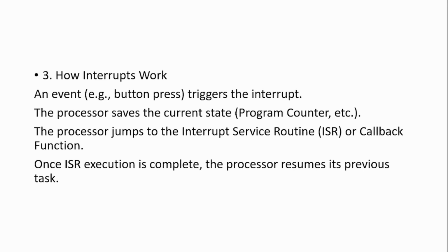I will not go into that much detail, but if you want, I can make a more detailed video. For now, just remember that the processor saves the current state. Then the processor jumps to the interrupt service routine or callback function. After completion of that ISR, it resumes its original task from where it was saved. So this is how an interrupt works.